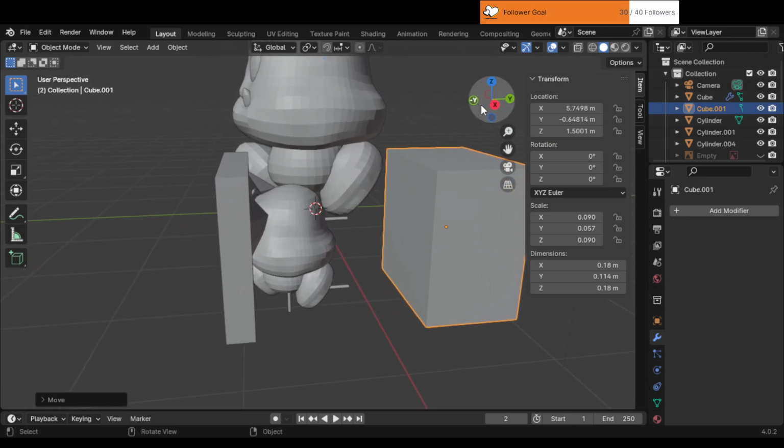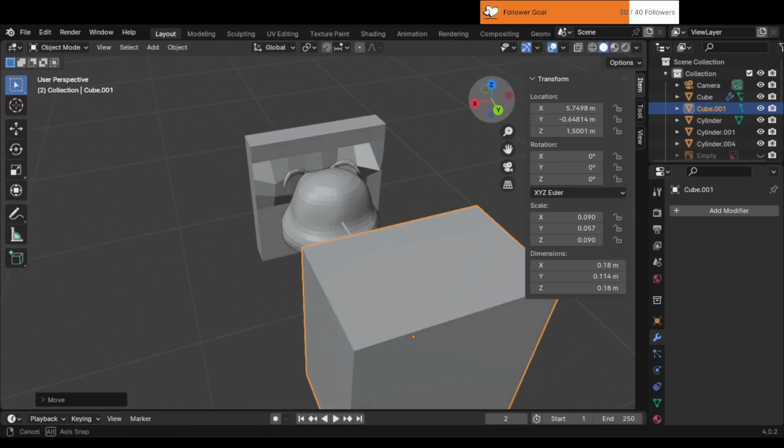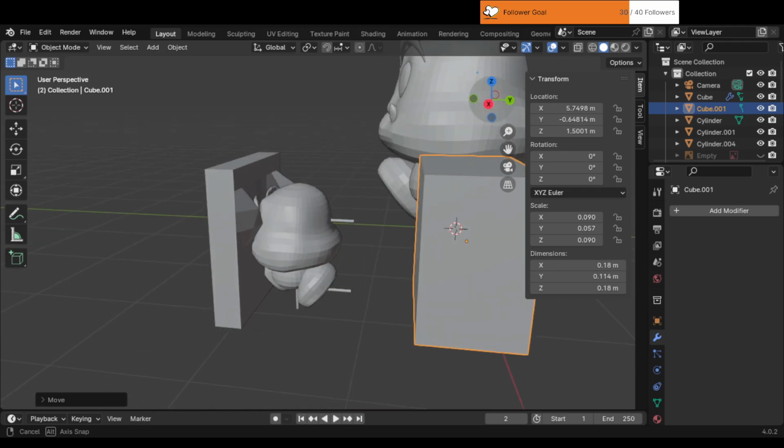2. Create a container. Add a mesh. In object mode, add a mesh to serve as the container for your mold. This can be a cube or any other shape that can encompass your model. Scale the mesh. Adjust the size of the mesh so that your model fits inside of it. Make sure the model is completely enclosed within the container.